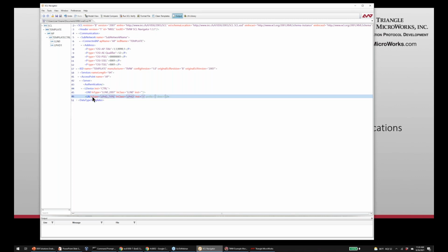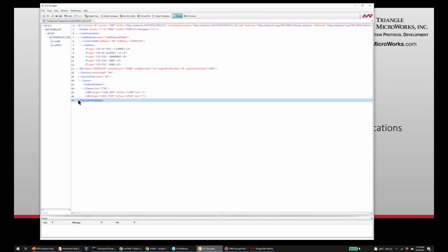LPHD represents the information about the physical device of the system, nameplates and that sort of information. So we pre-populate that. That's required for the device here. And so this is our basic minimum set for an IED.